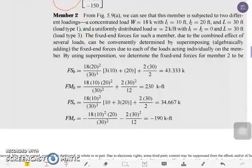So the first one, of course, is the formula for our concentrated load. This one is the formula for our uniform loading. So we have to add the shear force for the concentrated load plus the shear force for the uniform loading at the beginning of the member. Simply substitute the given values for our variables, and we now have the value, which is 43.33 kips.